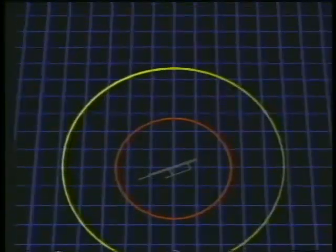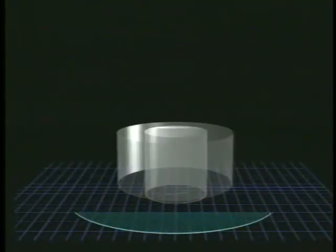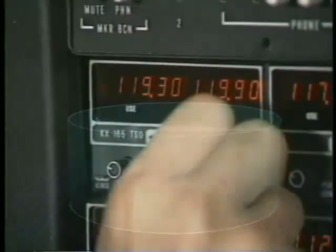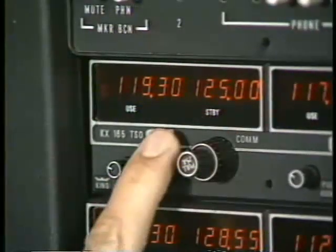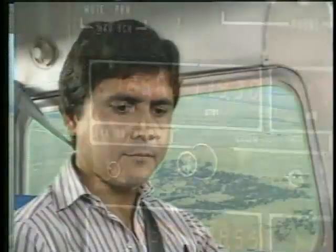If you're approaching an airport in Class C airspace, you must establish two-way radio communications with ATC before entering the outer circle. You are strongly encouraged to make the initial call within the outer area. Let's take a closer look at the procedures for entering Class C airspace. Listen to the ATIS as you approach the 20-mile outer area. "Jensen Airport, information Sierra. 1445 Zulu weather, temperature 76, dew point 44, wind 160 at 1."